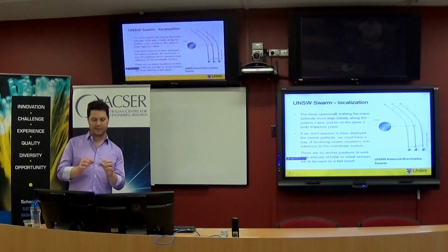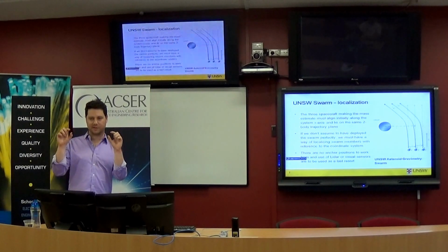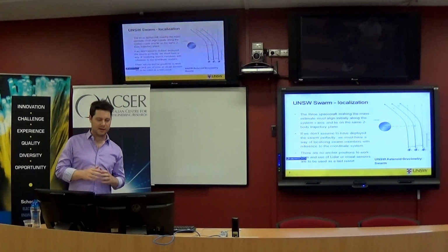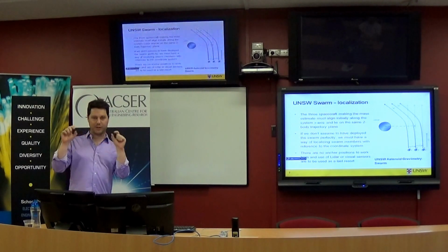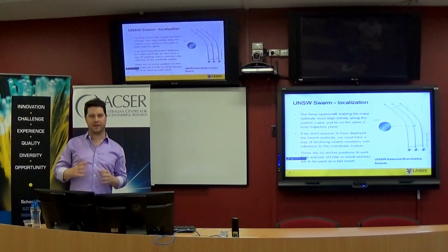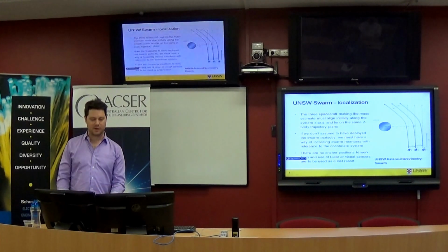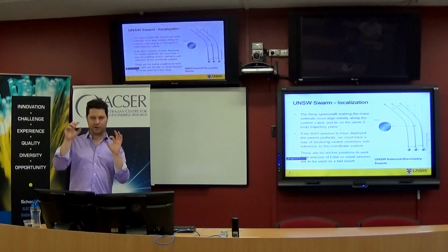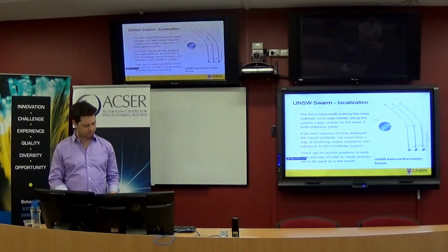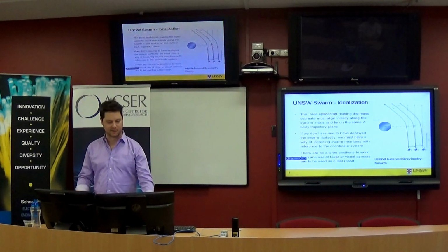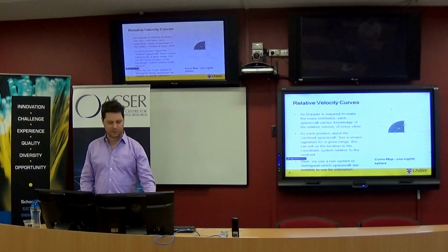So the hope is that we'll find two other spacecraft that are in line enough to make the calculations work, and to find out which two within a swarm of an arbitrarily large number, say around 100 members, we need to be able to localize where they exist. And the reason we do that is that there are no anchor points to work off, so we can't use a GPS style solution, unfortunately.